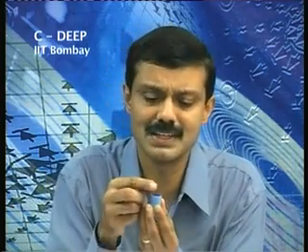So there are 4 terminals: primary winding and the secondary winding. On top it is written 1:1. It implies that the number of turns in the primary winding is same as the number of turns in the secondary winding. So this is a pulse transformer used to isolate the power circuit from the control circuit.